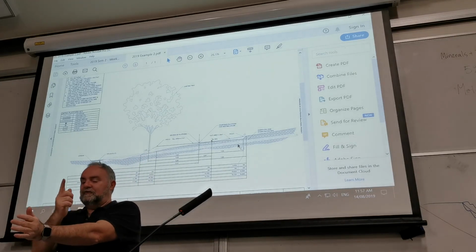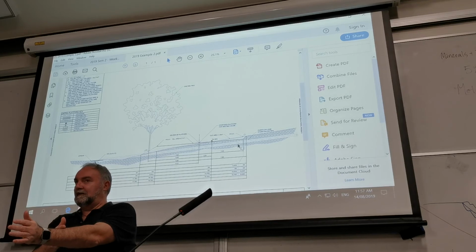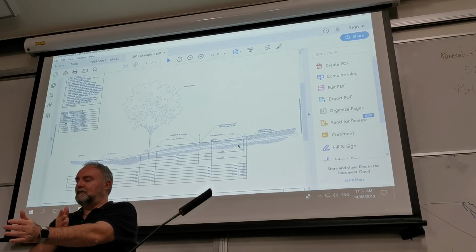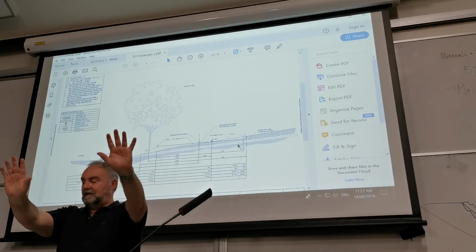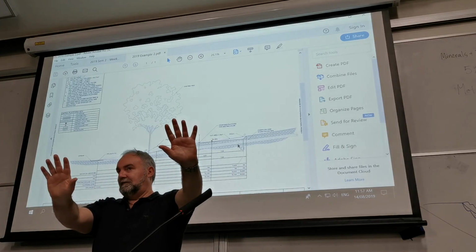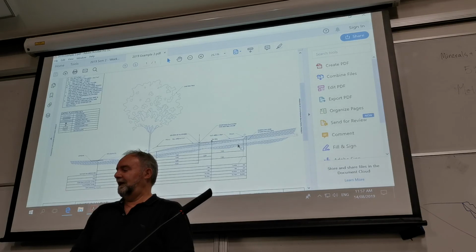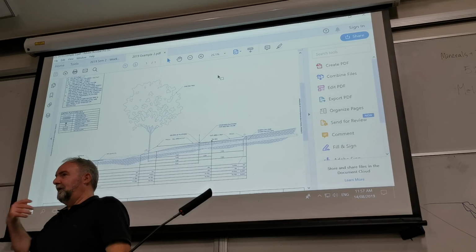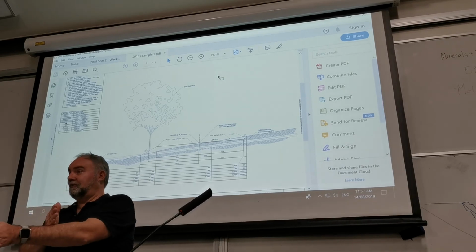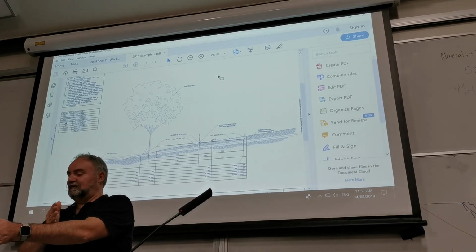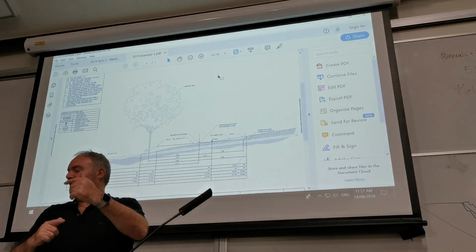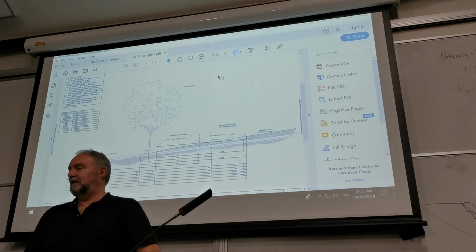Where it crossed over, there should have been a centre line in both directions, like in your sketch for Ingrid in week 2. And then when it was in the distance, it was dashed with no centre line. Got that? So you had behind, show, cross through, solid, centre line in both directions, and in the ground, dashed each side, but no centre line.